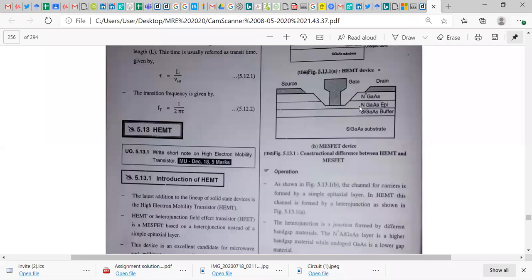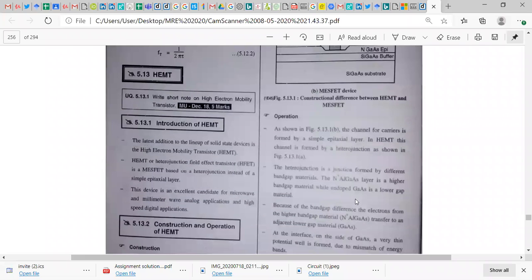If this were highly doped, N+ or even N++, there would be a large number of electrons, and the entering electrons would experience collisions. But as the number of electrons is very small, there will be very few collisions, and therefore mobility will be higher for the electrons.